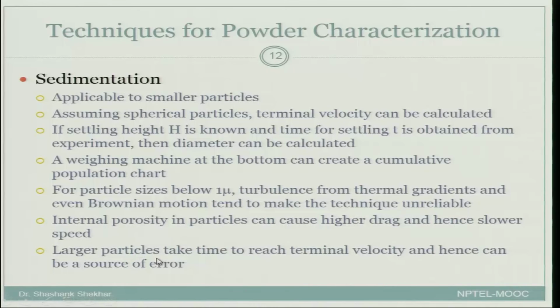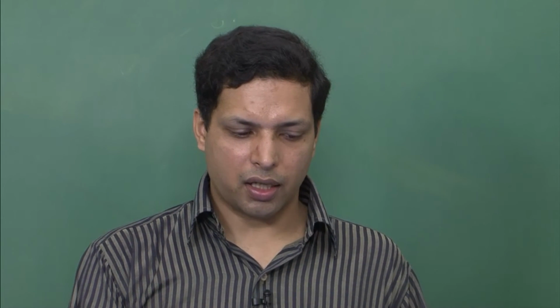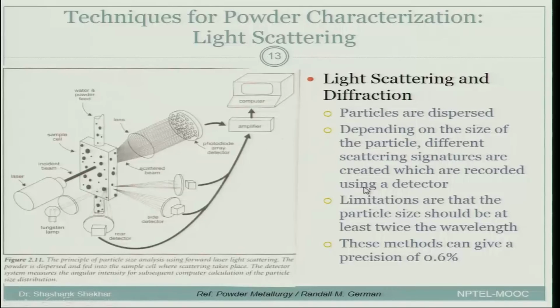And the last limitation we have already mentioned: large particles take time to reach terminal velocity and hence can be a source of error. So, the idea is that there will be techniques and there will be limitations, and so far we have looked at the imaging technique, the sieving technique, and this is the sedimentation technique. Now, similarly, there are some more sophisticated techniques.